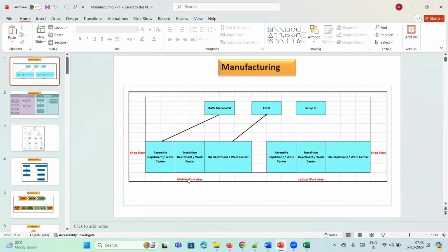In every production line, the last operation must be a count point. That means the last operation we must record in the application manually, marking that the operation is completed. While creating operations, by selecting the work center, you associate your operations to a particular work center, so that you define it only once and can reuse it whenever required.